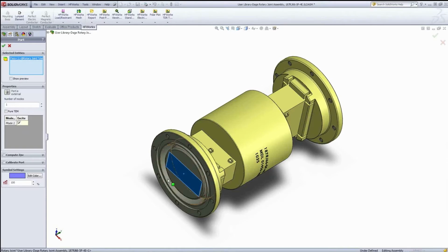Now, you also need to compute the impedance at the port. The software by default will compute what we call the power current impedance. It computes the power and the current and uses the definition of power, basically half Z I squared, and from that it will figure out the Z at the port.